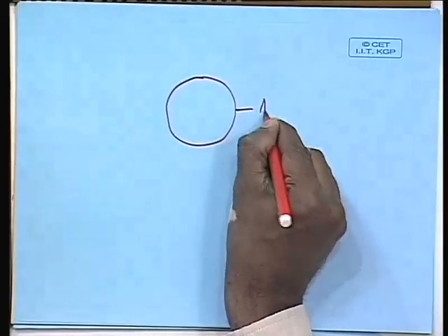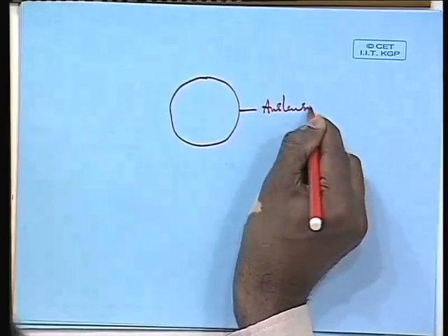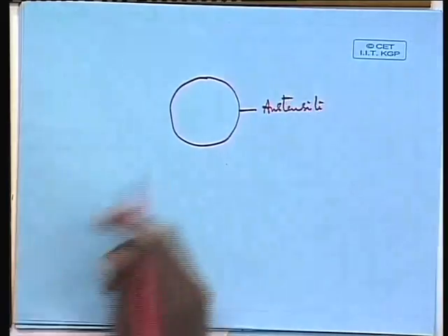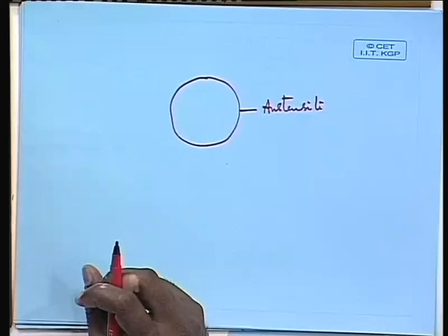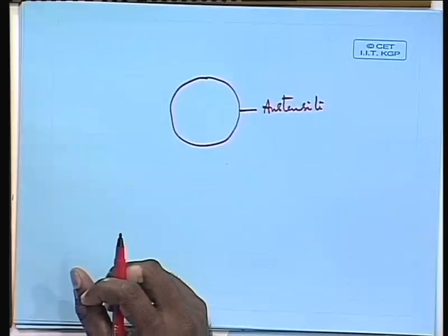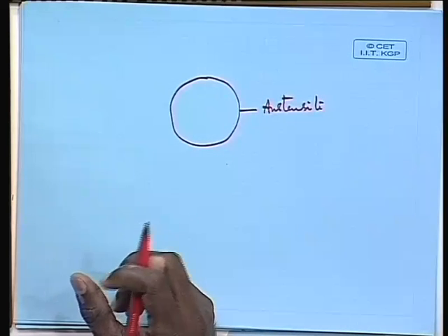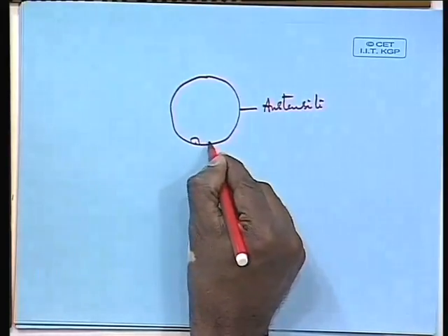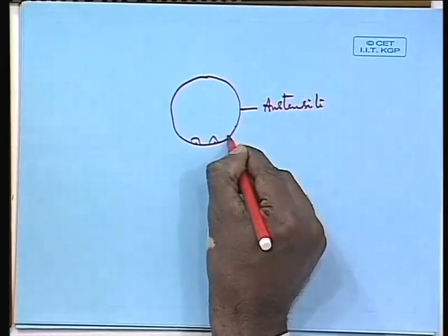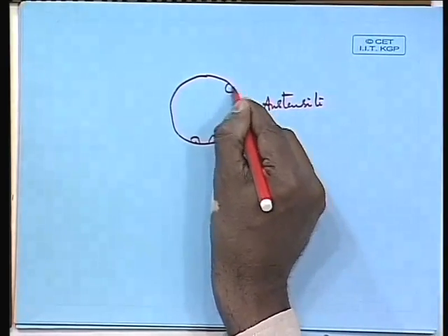This is austenite, and when this is being cooled, what do you expect the ferrite grain size to be? Will it be equal to that of the austenite grain? Basically, because we know grain boundary acts as a nucleating site, a number of nuclei can nucleate on the grain boundary in different regions.